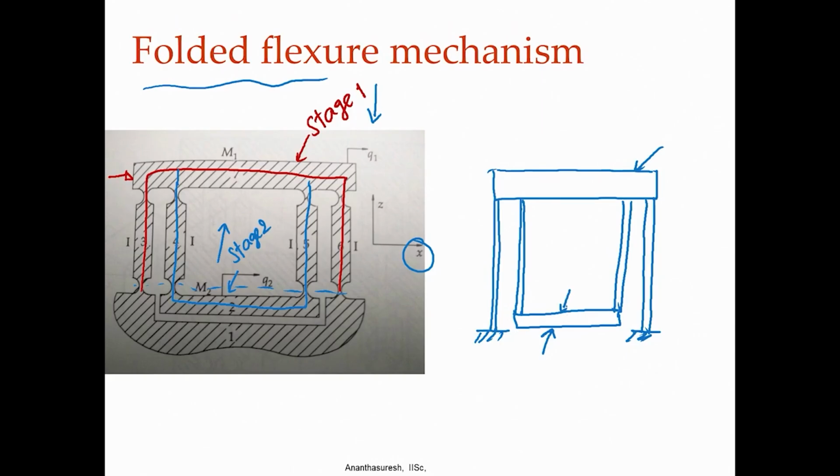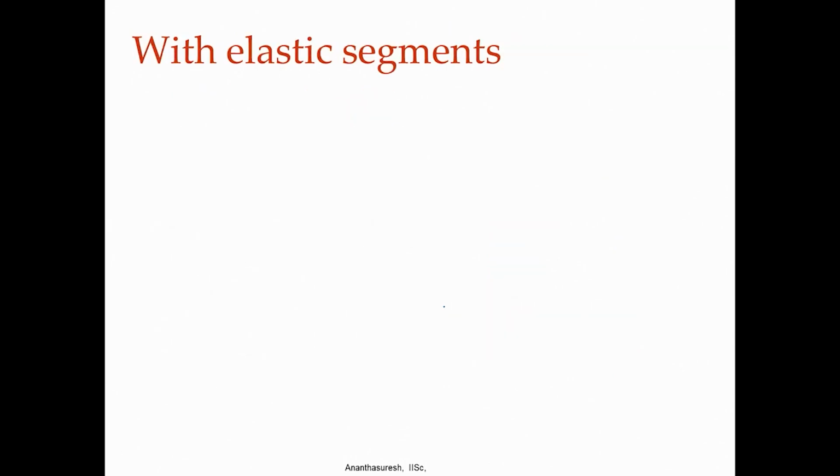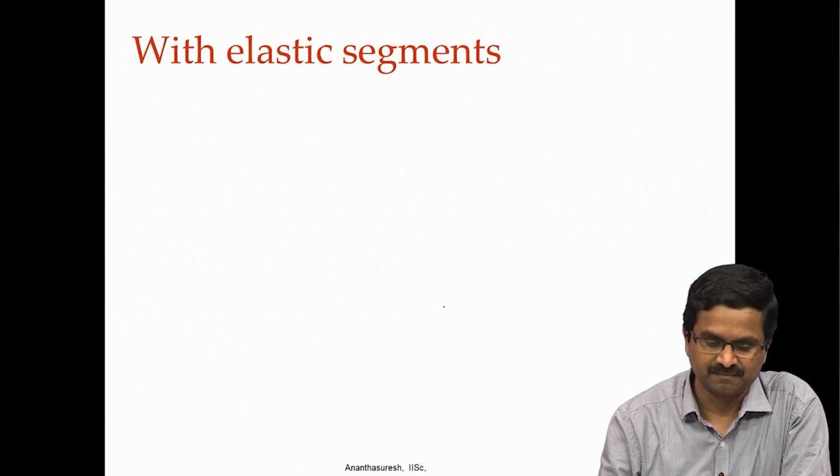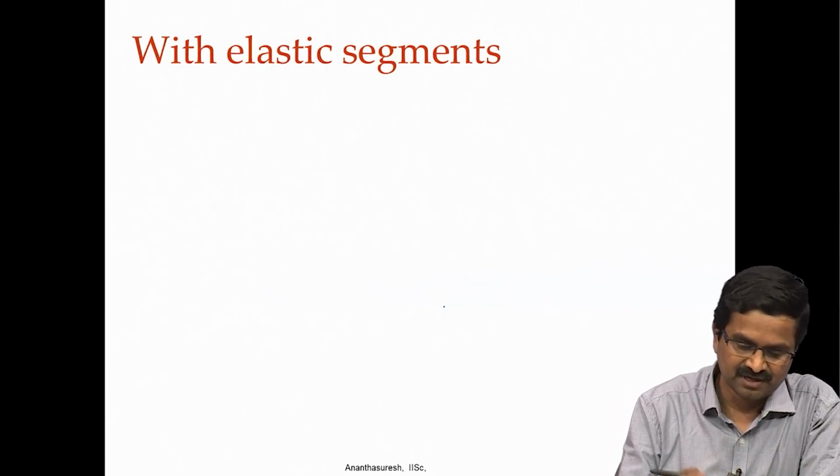Okay. Let us say we also want to find the stiffness. If I apply a force here, how much does it move? How much does this move? If it moves purely in the x direction, what will be this movement? Let us call it delta. We want to know what this delta is. If we know the geometry of the beams and their material properties, when I say geometry, the length as well as the cross section, right now we are taking uniform cross section beams. How do we do that? That becomes our strength of materials, as we incorrectly call it, or mechanics of materials.